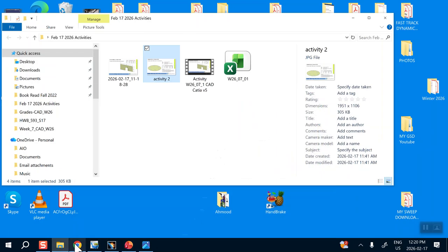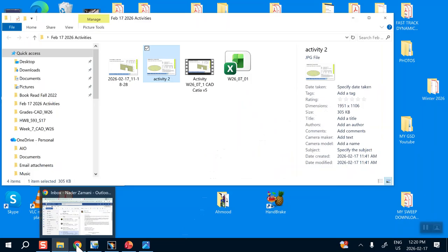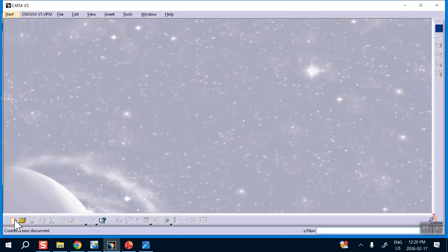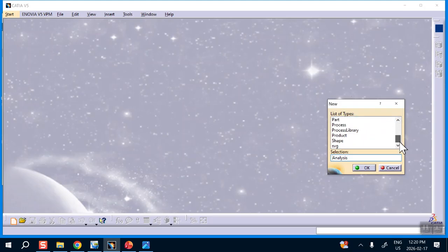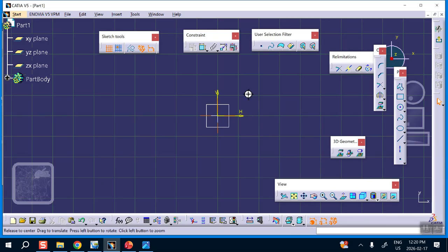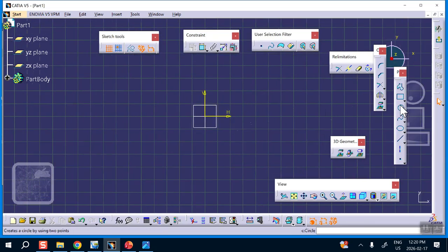Let me go here. Where is it? Yeah, CATIA. Because we're dealing with surfaces, immediately you go and do a part. Generative shape design, that's really what I meant. And let's go and make a nominal part. On that plane, I will sketch a circle. To make my job easier, I'll center it like that, okay?